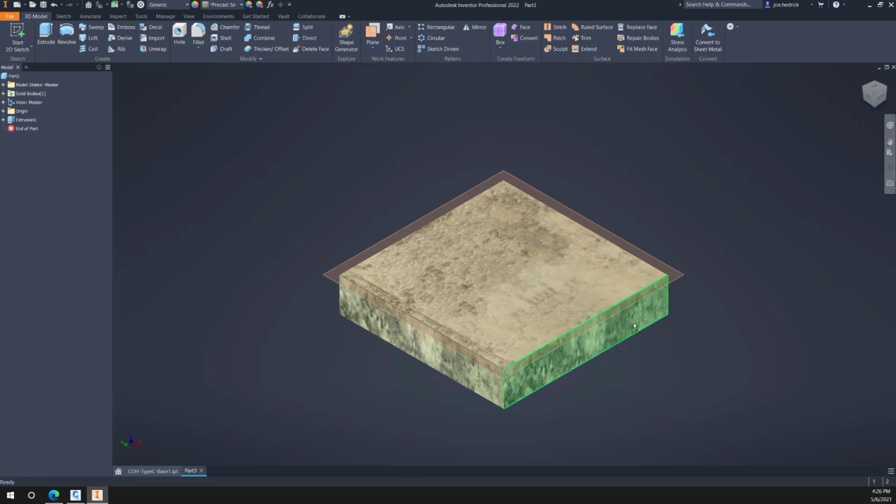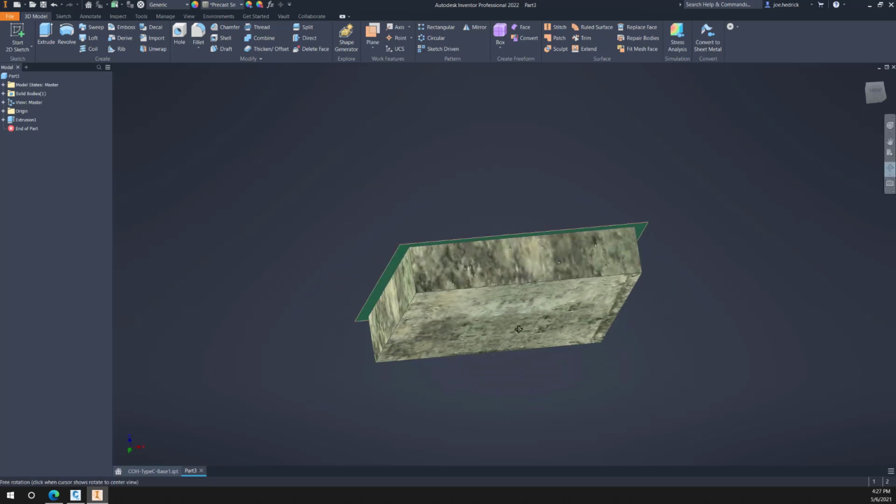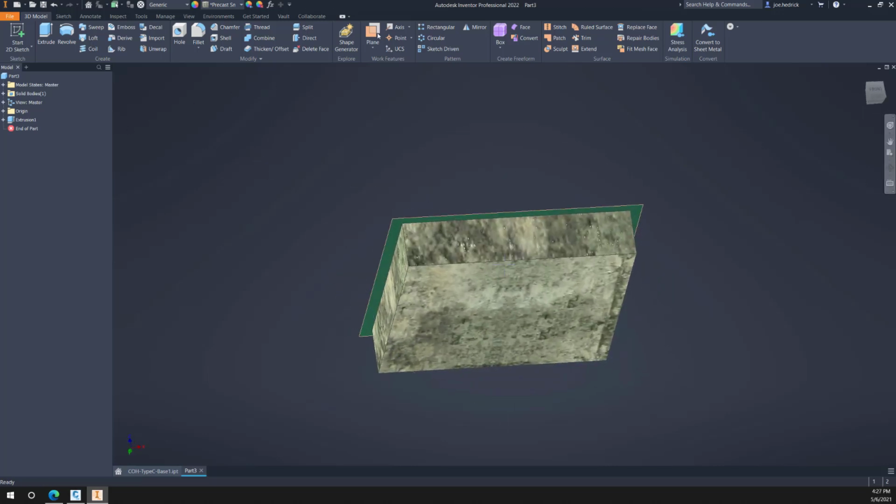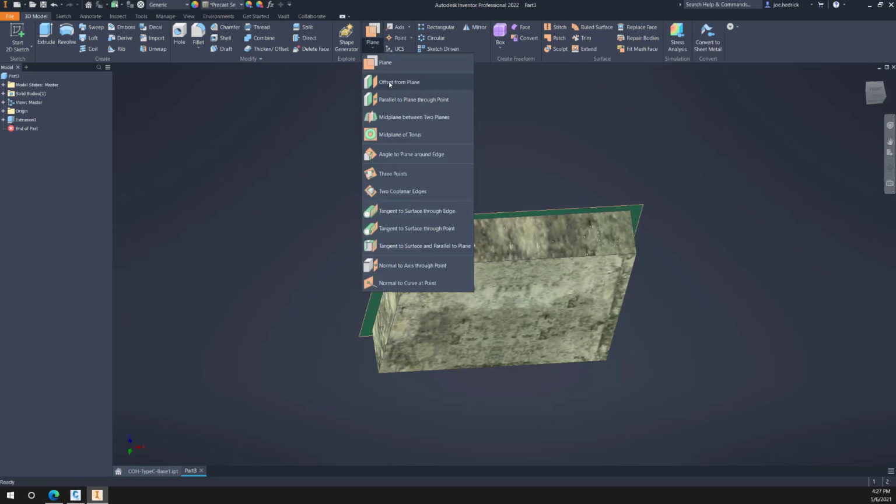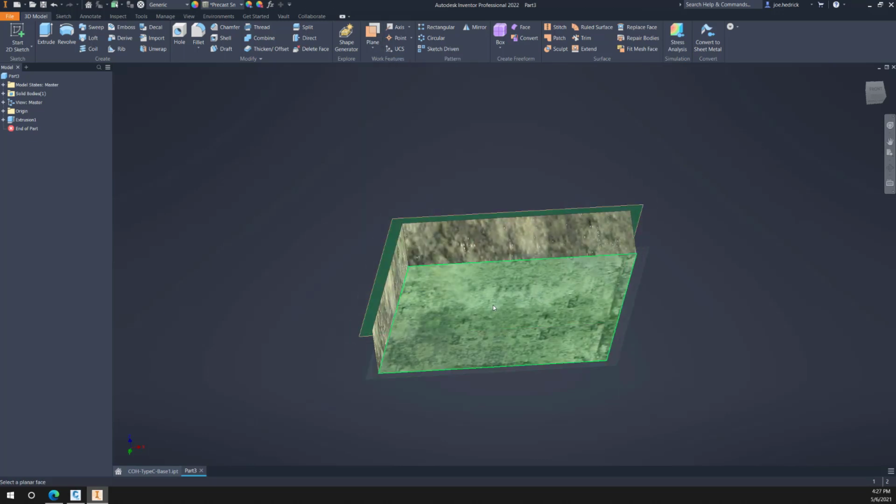And we'll model out the actual opening for the curb inlet here in a moment. But let's go ahead and get the riser and the wall thicknesses going. So let's tip it up on its side. We're going to offset this 0. And maybe instead of work plane, I'm going to call this riser top.